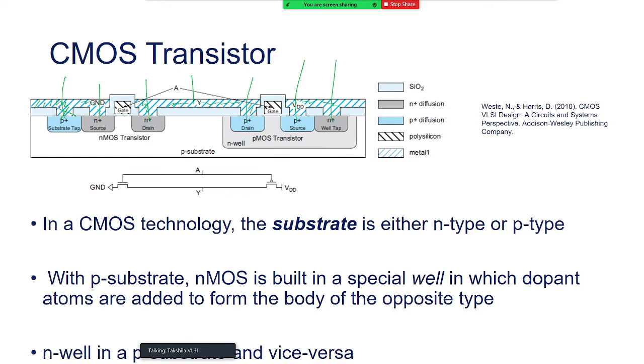Because in the layout I define the contacts. You remember from the top view, here were my contacts, those little black squares. Those allowed me to have access to form the cuts, and when the metal is poured, the metal goes here, and that's how it gets connection. So the SiO2 layer is visible, N diffusion area is visible, P diffusion area is visible, polysilicon is visible, metal is visible. And look, this is the drain and drain of two transistors.